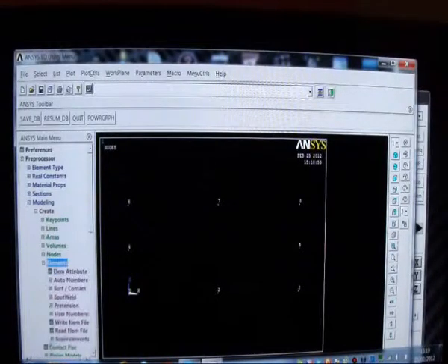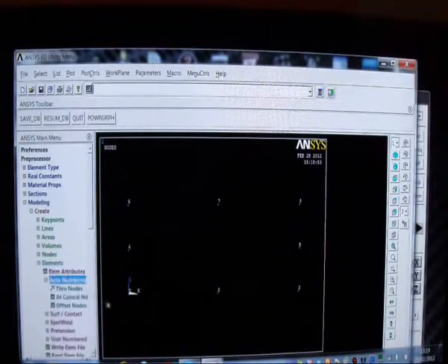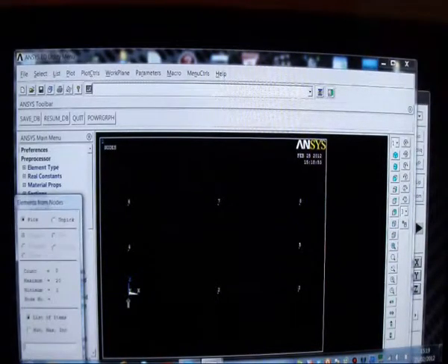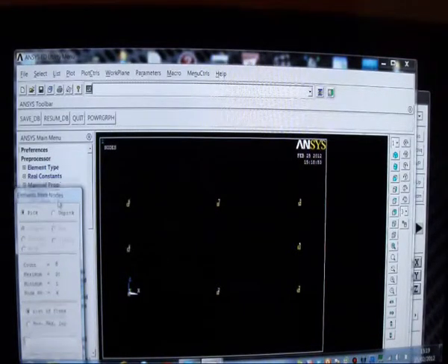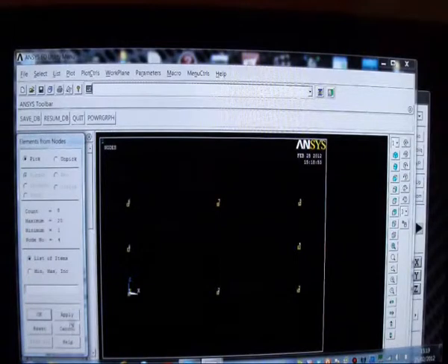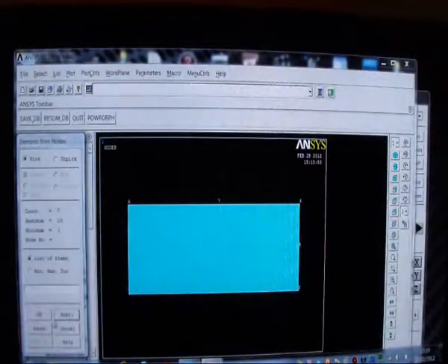So I pick elements there, and I pick auto numbered, and I've got to go like this: 1 there, 2 there. Wait a minute, through node, I haven't done that correctly. I put 1 there, 2 there, 3 there, 4 there, 5 there. And this must be done like that, or the element won't work. 6, 7 there, 8 there, and I press apply, and I've got my element.